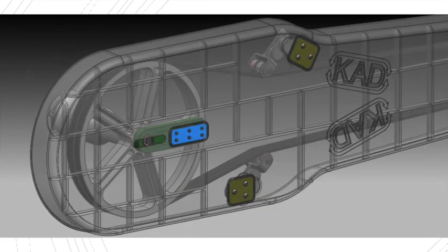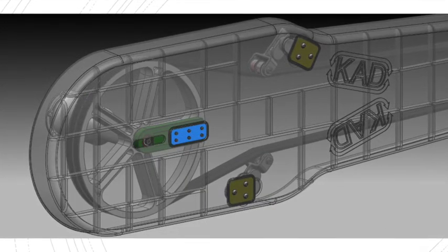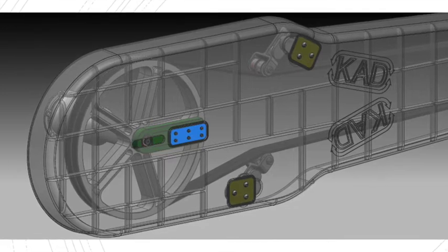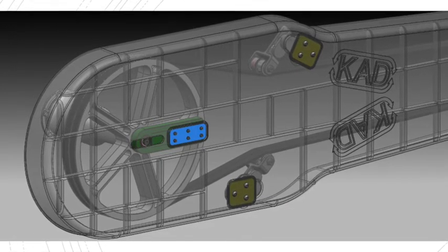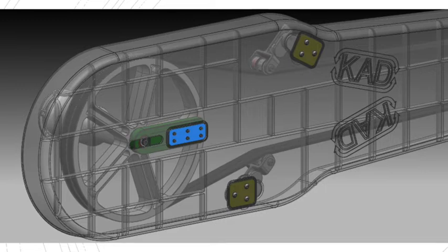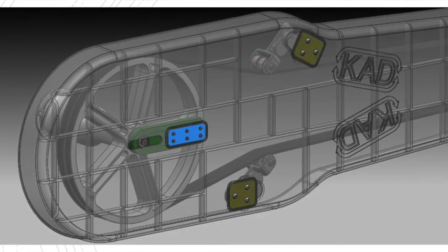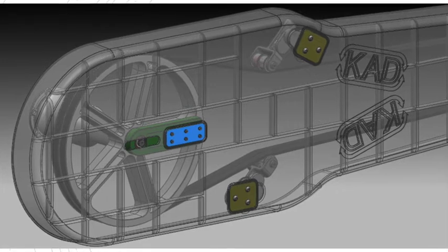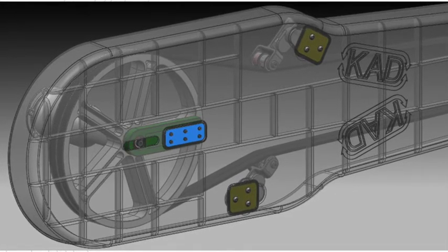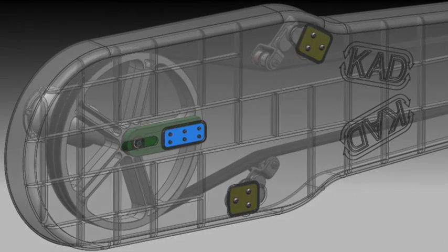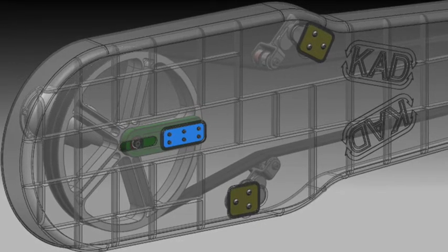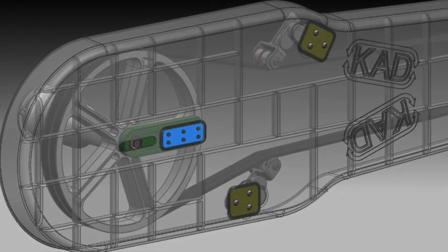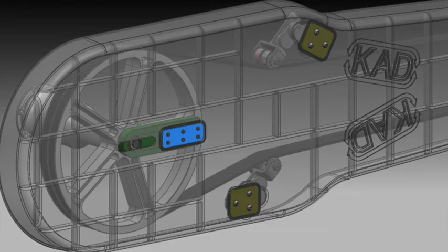Here is a close-up view of the belts on the left wheel gear with the tensioner. The belt guard is shown with semi-transparent material for visual aid. A ball slide, which is used to facilitate the changing centerline distance, is also shown. The ball slide, green, is mounted to the wheel gear and the belt guard.